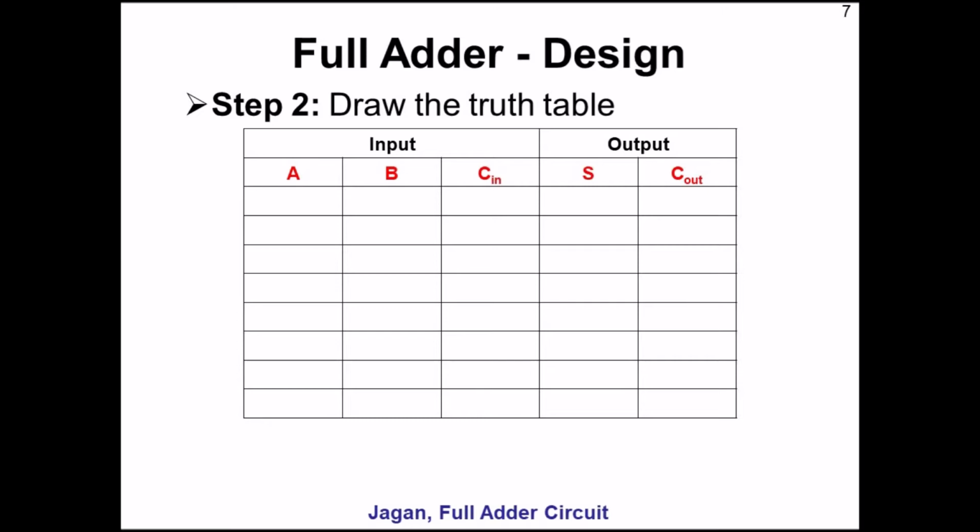So let's see what will happen if my inputs are 0. So I will get sum as 0 and carry as 0. And what will happen if I have a previous carry, even if my inputs in A and B are 0? Consider that I have the previous carry that is going to be added to the input. So I will get here the sum be 1 and carry be 0. And next possible cases, I will just go through the cases.